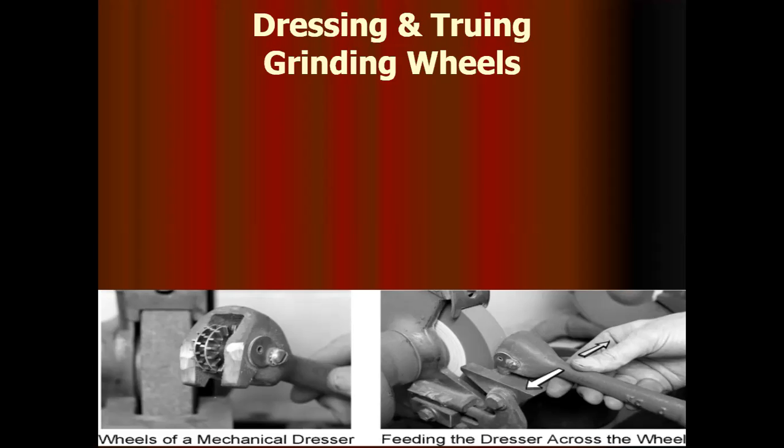Sometimes you turn these on, these wheels will have a vibration to them, and that's not a good thing. Vibration is not good on high-speed rotating equipment. So we use a dressing tool to hopefully address and true the wheel surface. It's kind of like if you've ever been a mechanic and you start to balance a tire,